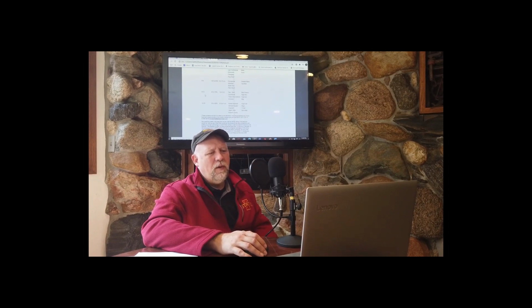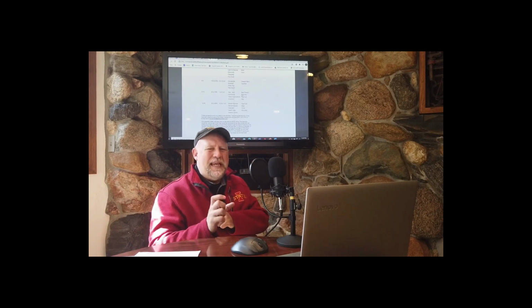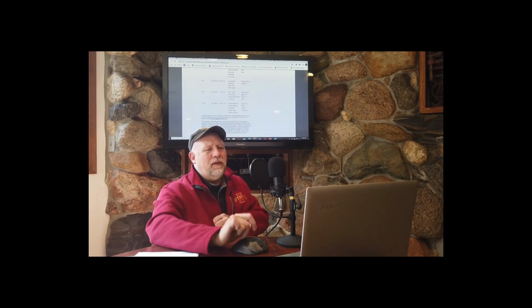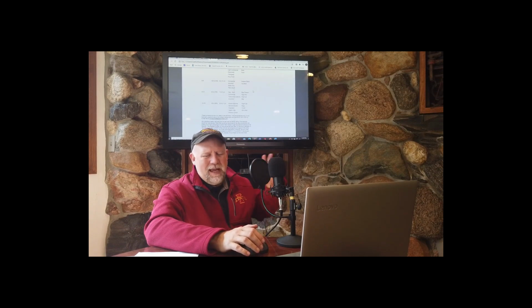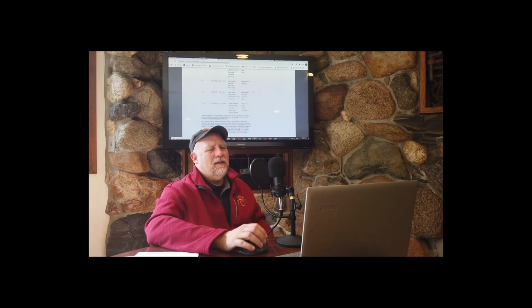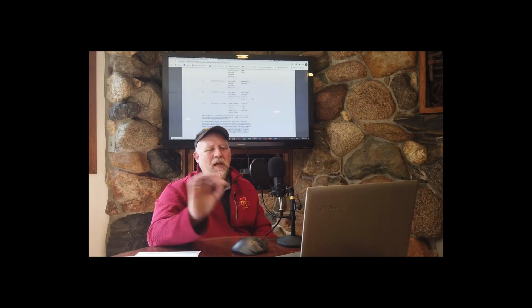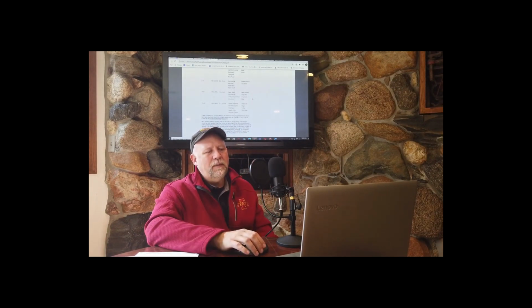Let's get to a better one. MERV rating of 9 to 12. Those are the ones that I would think of as your starting commercial filter. They're going to be the pleated ones, like in a box that they're pleated. Maybe they've had some adhesive, they call it a tackified agent, put on there to help grab that dust and dirt. You might also see rigid cell filters or bag filters. I've got examples of each of those here in a little bit.